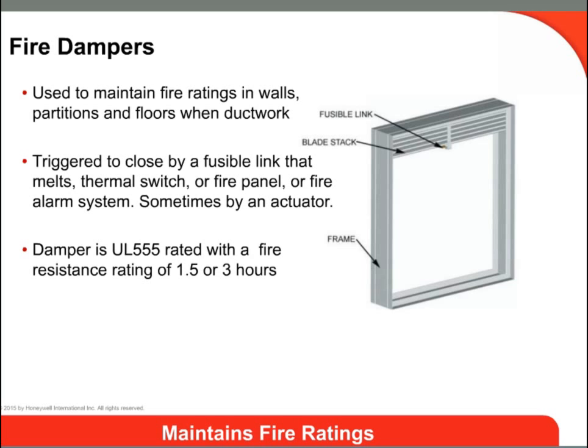Although the dampers are used in the ductwork, they are securely attached to the wall with breakaway connections so that if the ductwork falls away, the dampers will remain and maintain the integrity of the wall or floor. They are also used to isolate large air handling units. Fire dampers may be rated as static. These are used in systems where the HVAC system is shut down in the event of a fire. Or they may be rated as dynamic, where the HVAC system will operate during a fire.